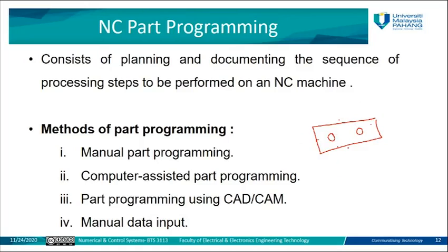So if you go, there are some tools or packages that come with this software from Autodesk, for example, which is one of the main developers of these programs, such as Fusion 360. There is a package you need to add to the software, and it will convert these drawings directly into a list of commands like G01, G03, G0, whatever is based on the drawing. It will generate the code.